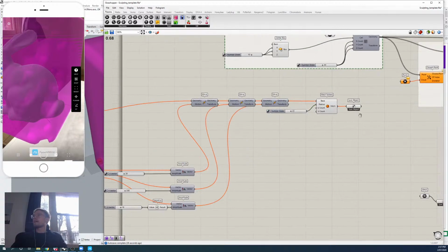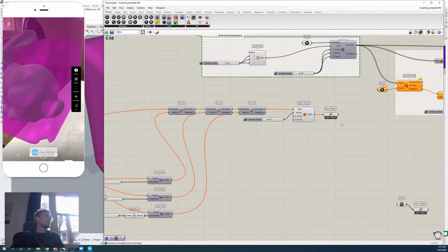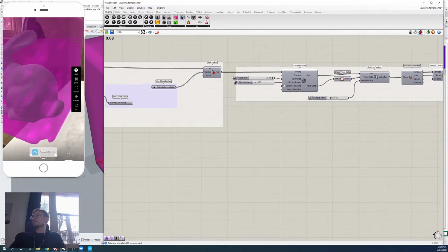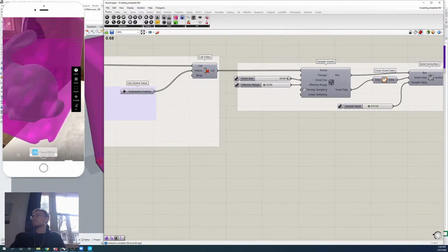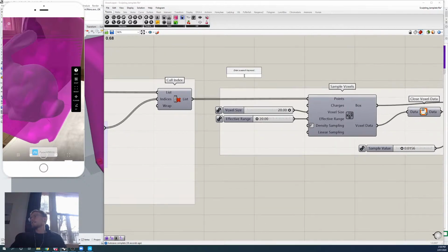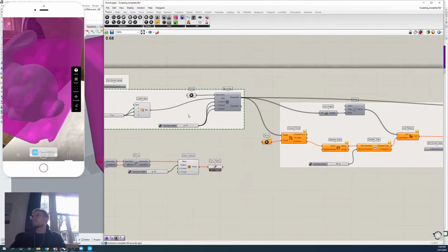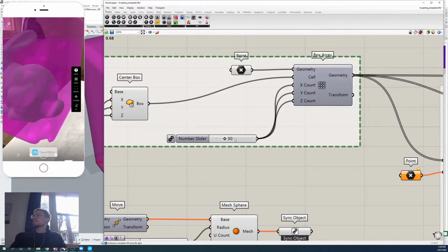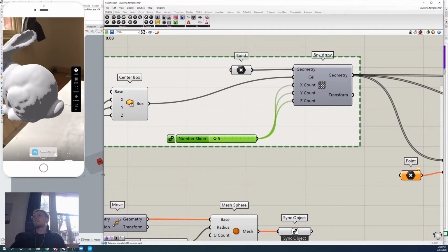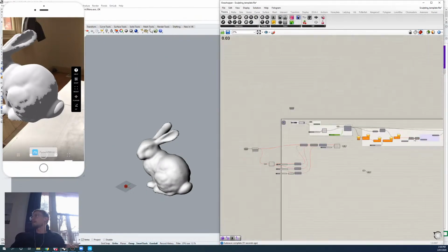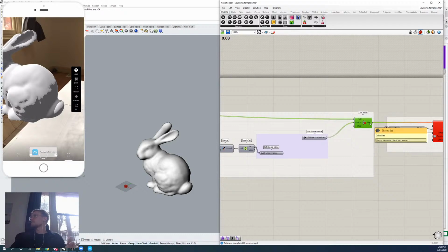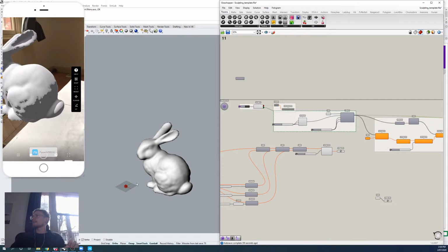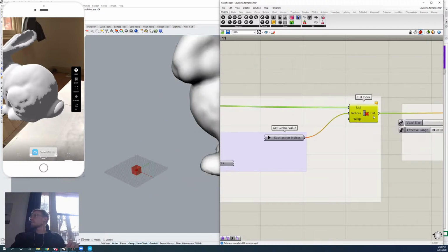So a few people are getting that error. I'm guessing it actually might be a computer issue or something. It could be if you're using a really old laptop as well, that might be causing the issue. You could try changing the box array to a much lower value. Maybe you could change it to like 5 just to test if it's going to work. Do I get an error when that happens? Yeah, I do, because I'm culling my whole list. But if you change that to like 5, what do you get then?